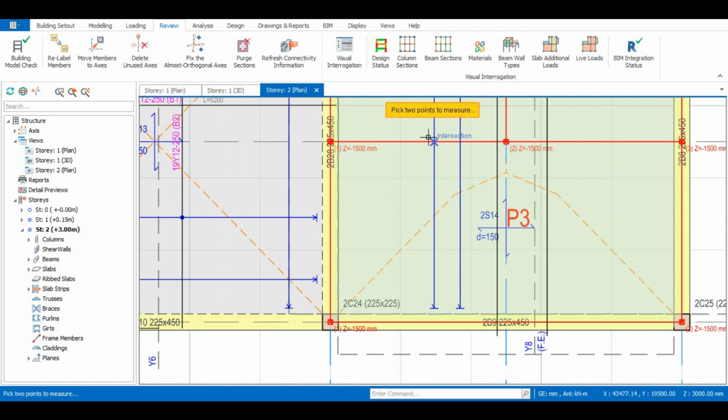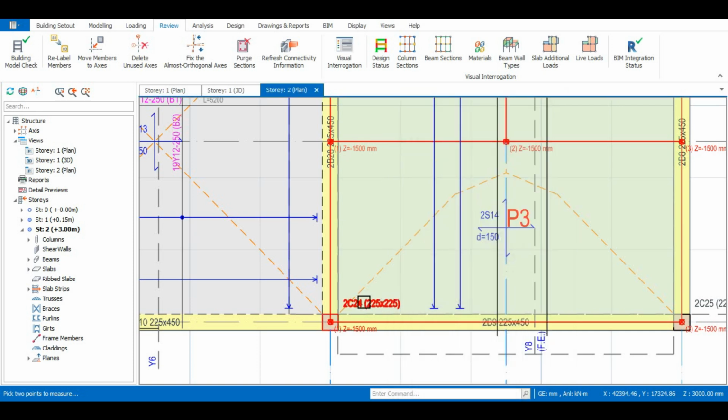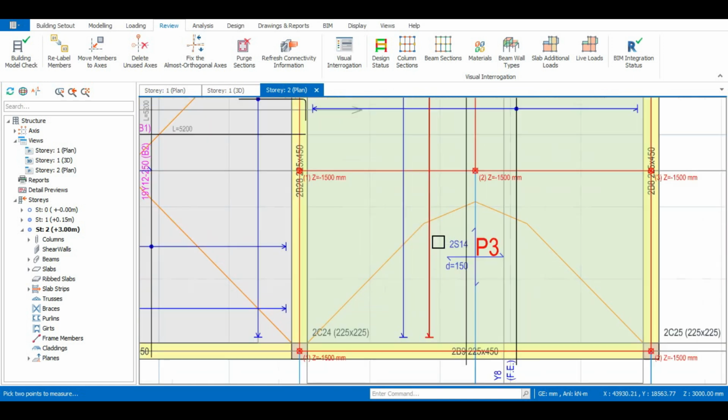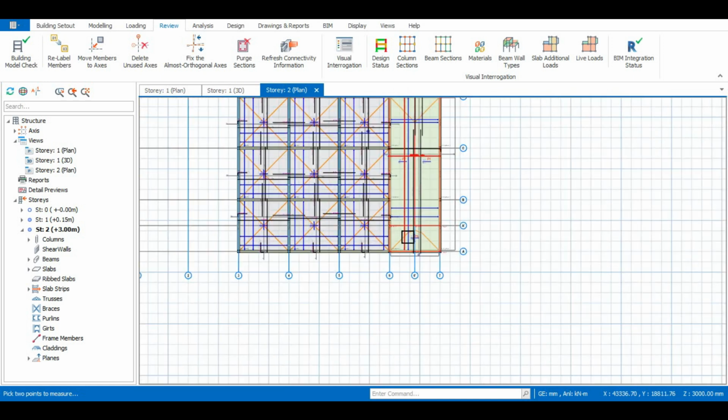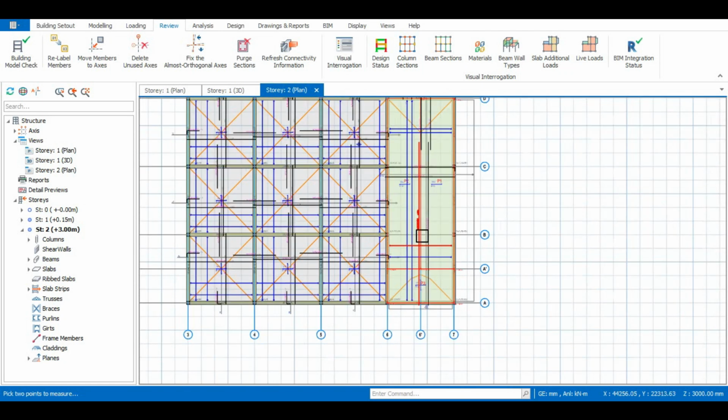This is where the landing stops, to here, and you have 2310, so you can skip that measurement. Then you can divide 2310 by the spacing. As you can see, I have here 2310 divided by 250 gives us 9.24. So which means you have 9 of the Y strip coming on top of this place, and whatever is left of that is going on top of the ramps, at the required 250 spacing. And that's about that, I guess, for this.